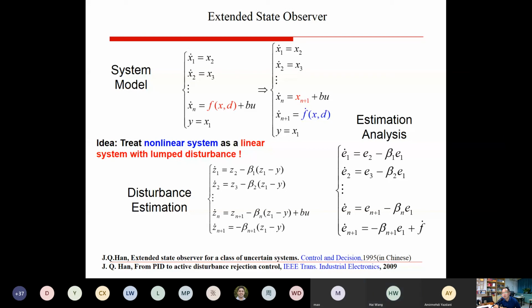So I suggest first you need to do the modeling to have a good, precise model. Then you can try the method. And for the model, the easy one is to do a linear system model identification, right? But if you want to enhance the speed, you have to add the friction. If it is all for high speed, the friction is not a big one. Maybe you need to consider the load torque, and have a load torque estimator.